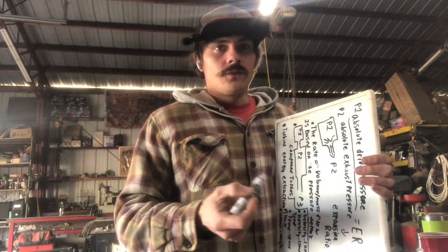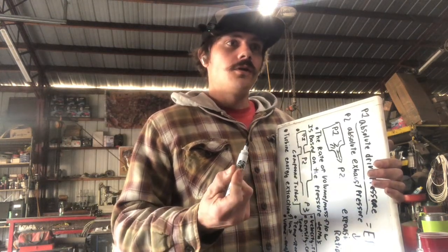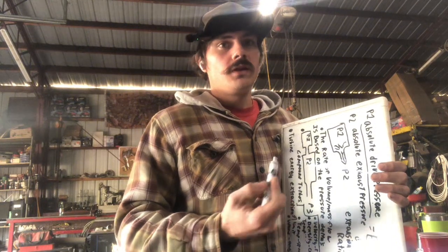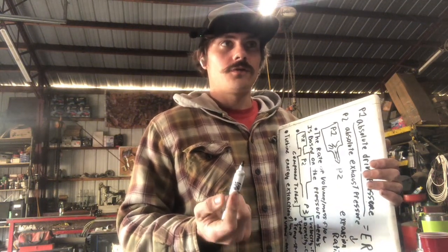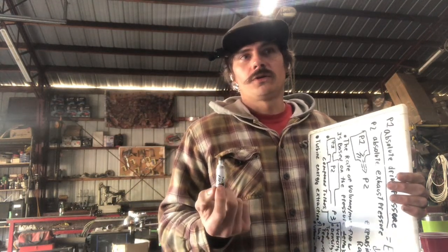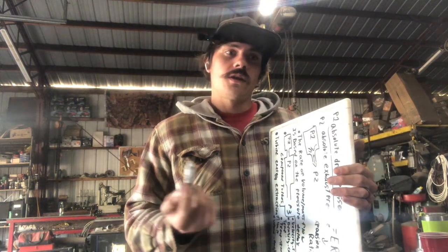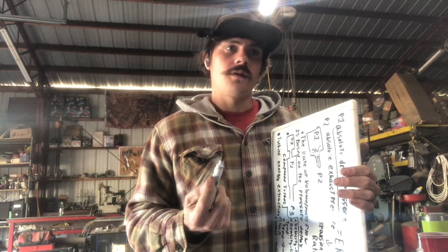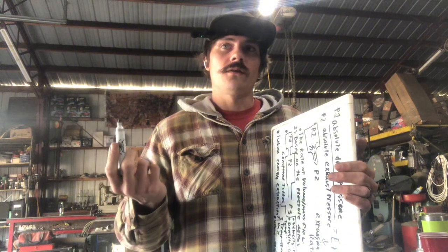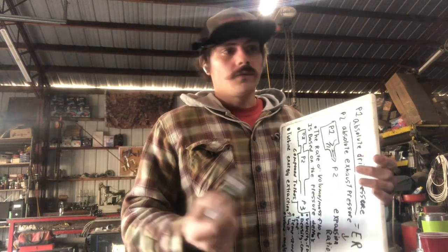And the other side of this is when people turbocharge normally aspirated designed motors, right? Your NA motors that are designed to be NA really do care about the drive to boost ratio at a very low drive to boost ratio, whereas motors designed to already be factory turbocharged, with the higher drive to boost ratio right out of the gate, the engineers account for that, and you don't see nearly the gains on systems where the head and cam are designed for that, versus if you take an NA motor at 2-to-1 and you drop it to 1-to-1, there's a big gain there.